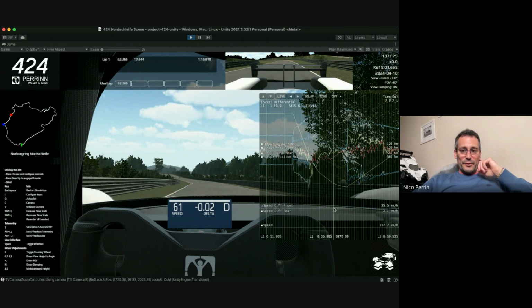At the rear, we also open the diff, but it's a scenario where the wheels want to stay together because we are not braking extremely hard on one, we're using one wheel. So even if the diff opens, we only have 2.5 kph wheel speed differential. It's what we call the bicycle effect, or the fact that one wheel, the outside, has to travel more distance than the inside wheel. So the outside is going to rotate a bit faster, by about 2.5 kilometers an hour. But at the front, there's 29 kph difference because we are locking one. Okay, so this is the diff.